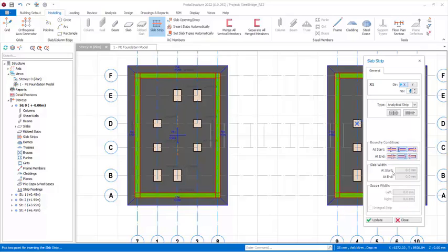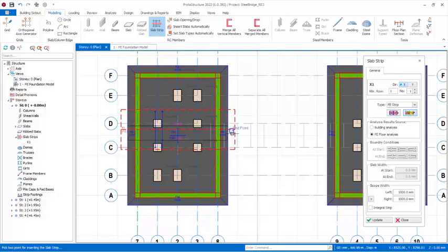Then we come over to the type of strips. We have the analytical strips right there. We wouldn't use that; we use FE strips, and then use this option for fixed band strips. This one we will be using. We are in the X direction, so we select any point right there. Take your hand across the reinforced concrete slab foundation, and hold the control key to have a straight line. Click to have the bounds placed successfully, just like this.